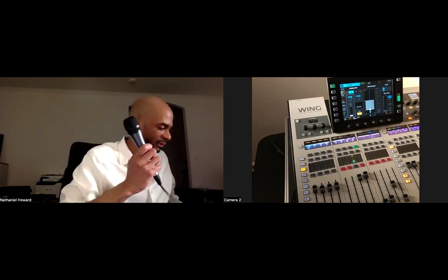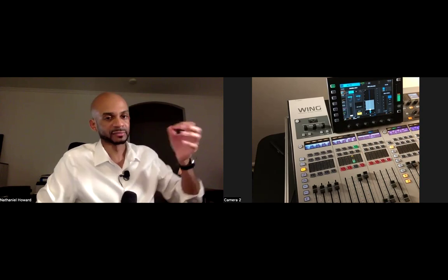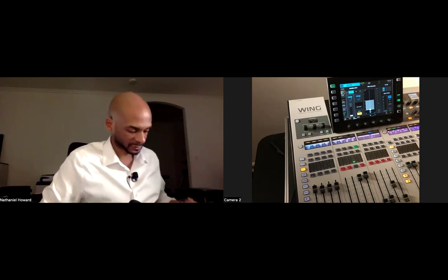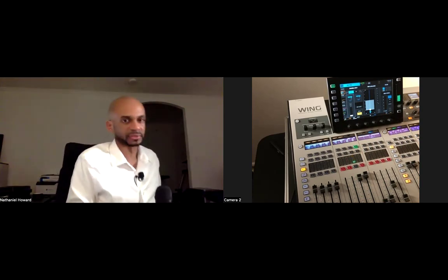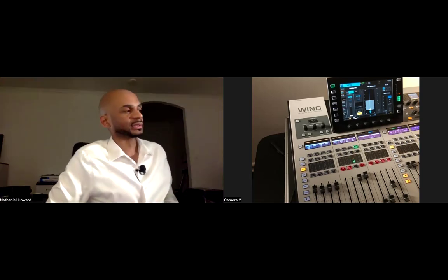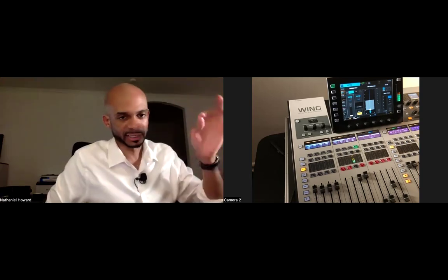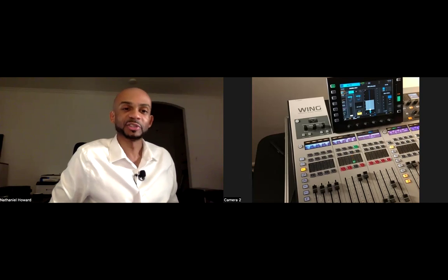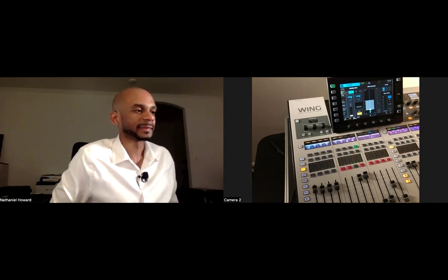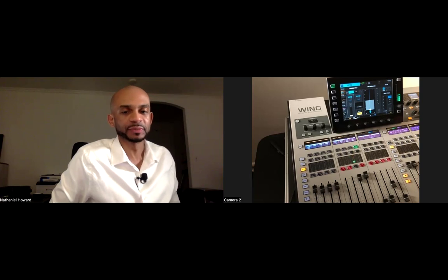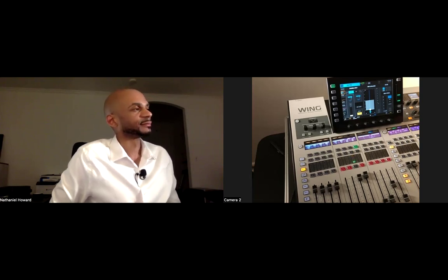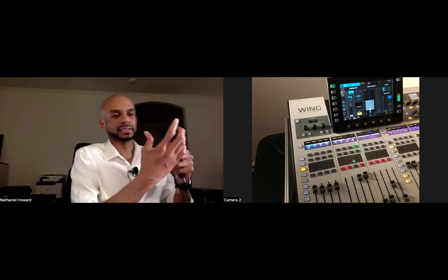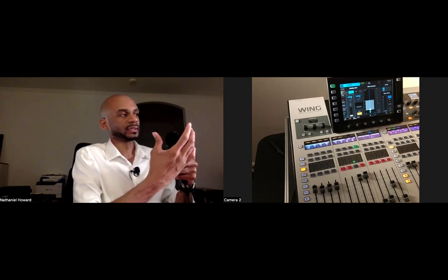It's normally set and forget. Every once in a while, you have to raise up the gain for certain situations, for example, somebody who is very, very soft-spoken, but normally you set the gain and just leave it alone for a good amount of time. You won't need to touch it. I recommend that you don't touch it unless you know how to re-EQ speakers, because what can happen is that when you raise up the gain, you're opening up how much the microphone captures.